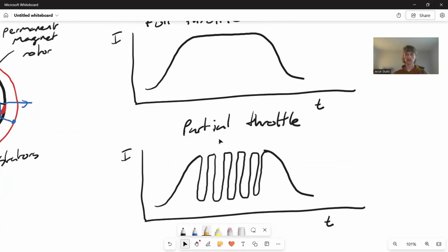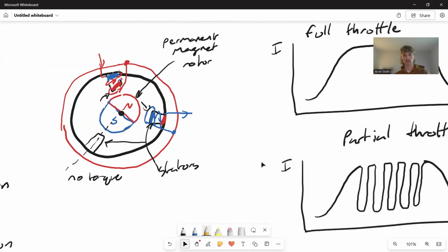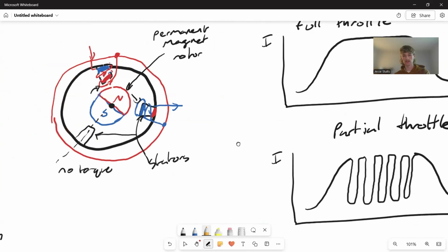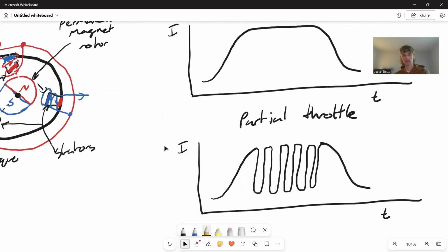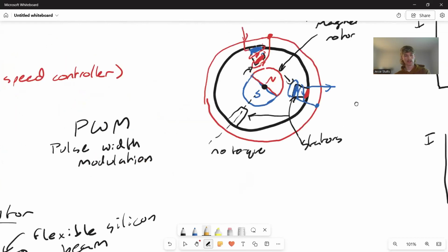So this is done extremely fast so that it does not jam up the motor, and the motor still runs smoothly because the motor itself is going, depending on the electric motor, possibly 12,000 RPM. So the pulse width has to be much faster than that while it is in the correct phase and orientation to get through this entire curve.